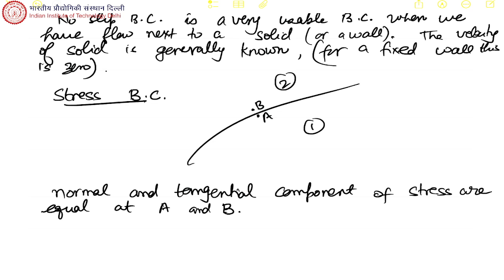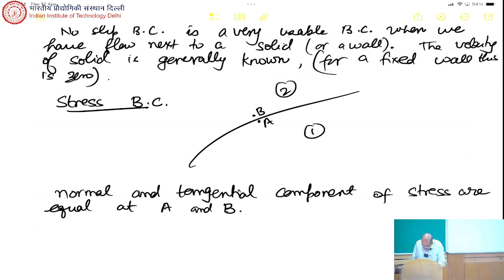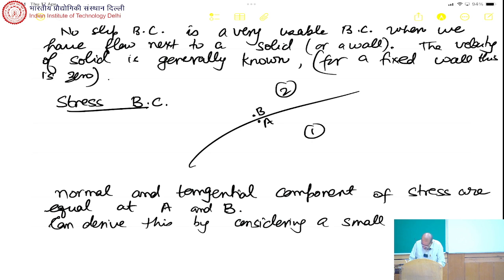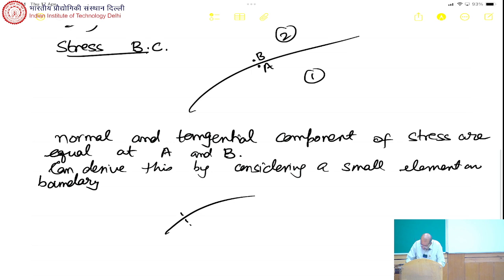Now, again, as I said, the tangential component of stress is equal if you make a small element on the boundary. So, you can derive this by considering a small element on the boundary and then doing a force balance.